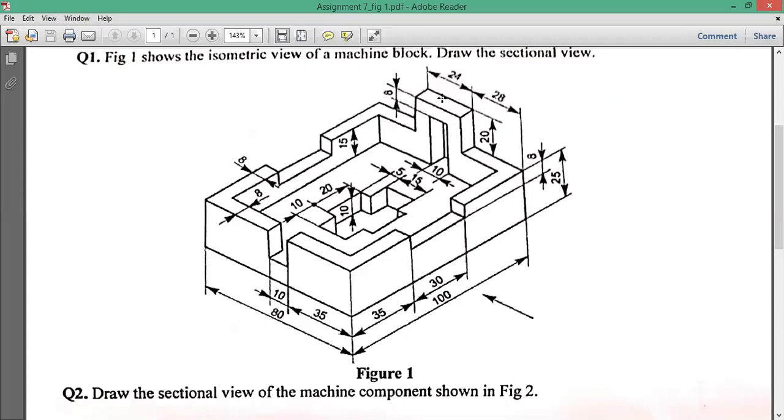That means when I break through the middle, we can specify one joint like this. That means that is also the section where we are breaking the material. So that also I will show in AutoCAD, because the distance here is given. How much distance? 8. So I have to specify the 8 distance by the hatch lines.